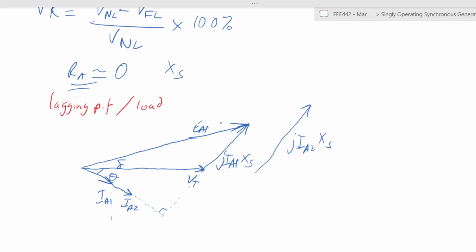So what then happens is, of course, it has to be connected to the terminal voltage. So what happens in that particular case? Now, your terminal voltage, whereas we have been saying it will remain constant, may not be able to remain constant. Why is that? Because this instantaneous increase in the load supplied happens in such a way that you are not able to change the field current, right?